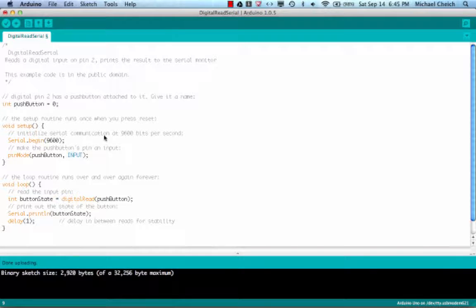So that's pretty much it. Again, I just want to recap this. If you're using pin 0, just be aware that you need to have it out when you upload the board, or you might have some issues. You don't want a circuit connected to it when you're uploading. And if you're going to be receiving data a lot during the program, that also might cause issues if you're using pin 0. But if you're not receiving data, then hey, it's fair game. Now, pin 1, if you're not transmitting any information, if you're not using the serial library, then it's fair game. So don't be afraid to use pin 1 or pin 0. Just know when they're going to be utilized by the Arduino, and there you go.